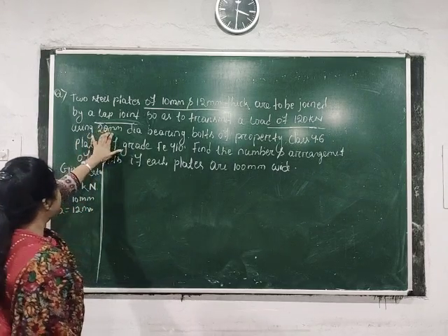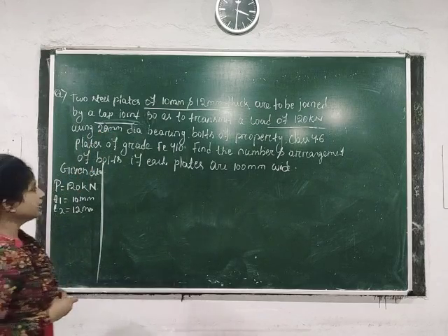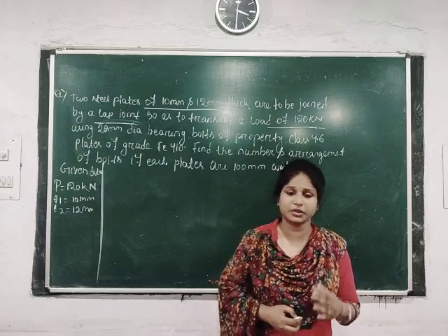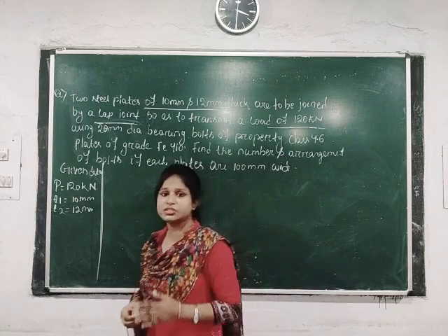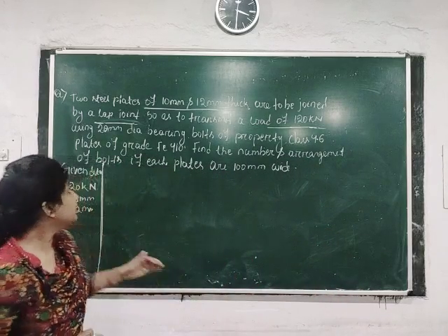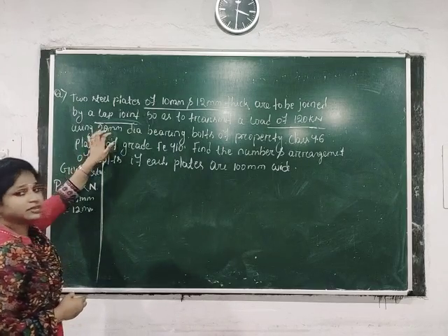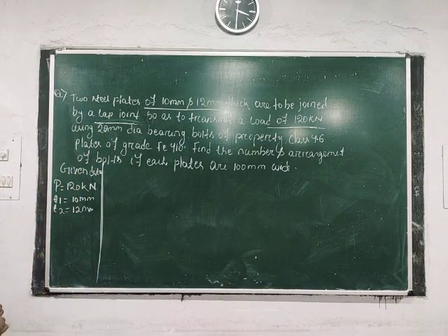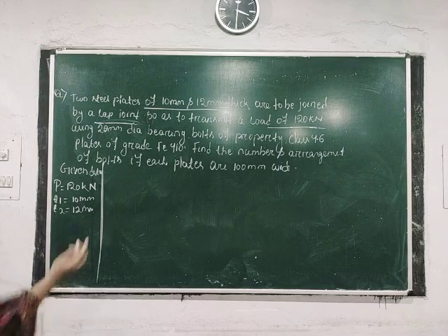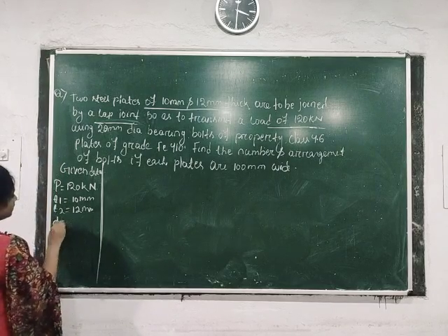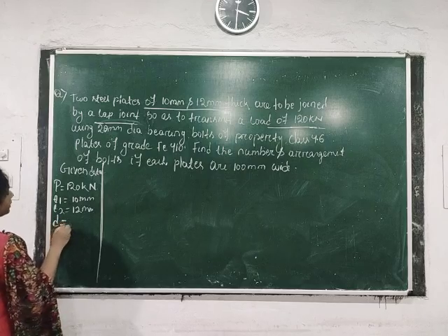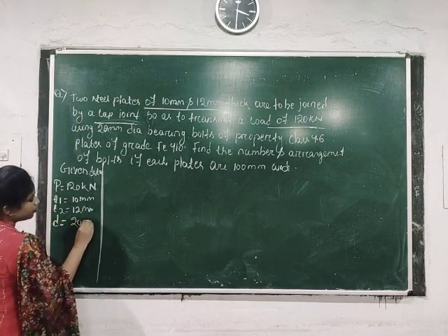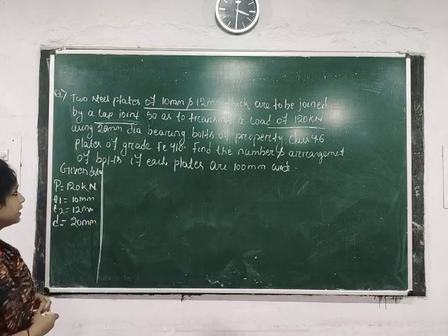I have discussed that if the bolt diameter is not given in the question, then we can determine the diameter of bolt from the Unwin's formula. As here the diameter of bolt is given, there is no need to determine it from the Unwin's formula. We can take the diameter given in the question, that is 20 mm.